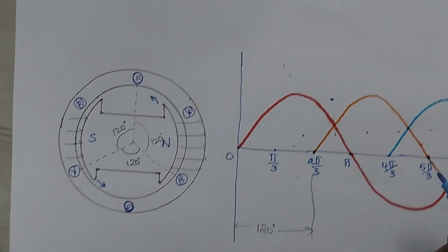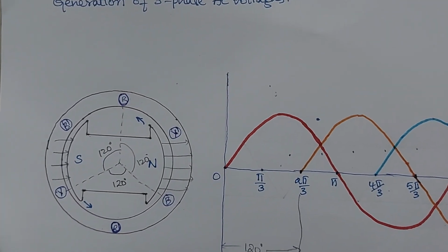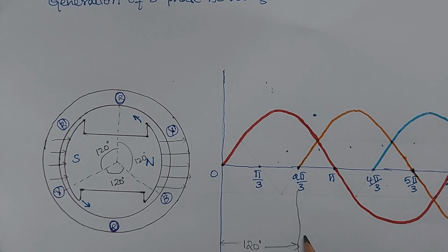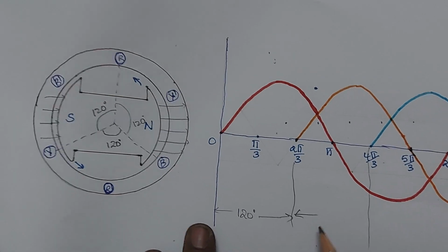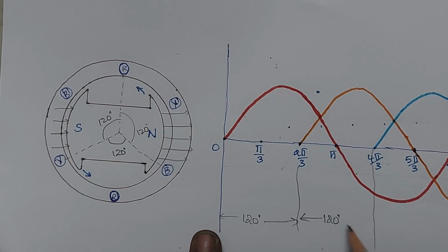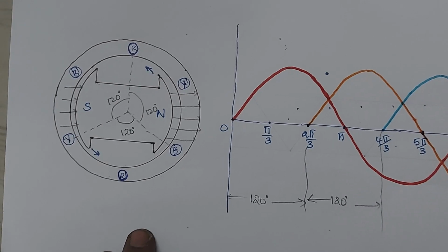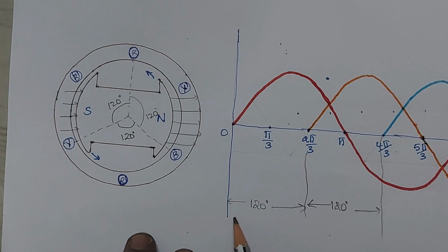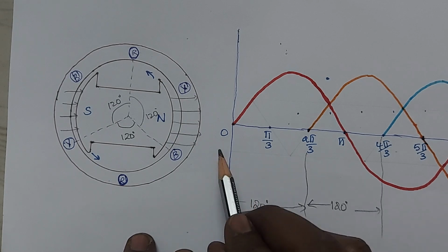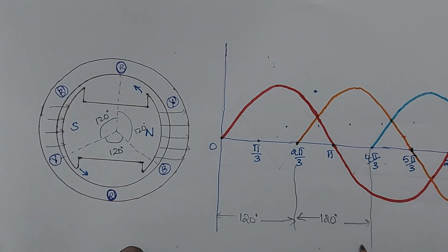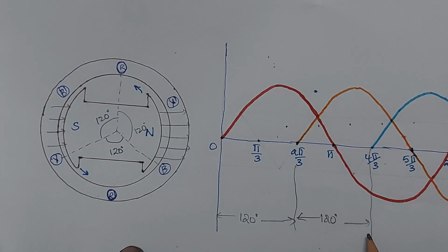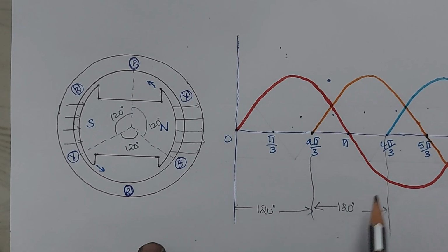Now the previous cycle, say here from this Y waveform, here one more 120 degrees is there. So if you take from the R phase, it is totally 240 degrees. From the R phase, the B waveform will start at 240 degrees. So that's why this is the way.